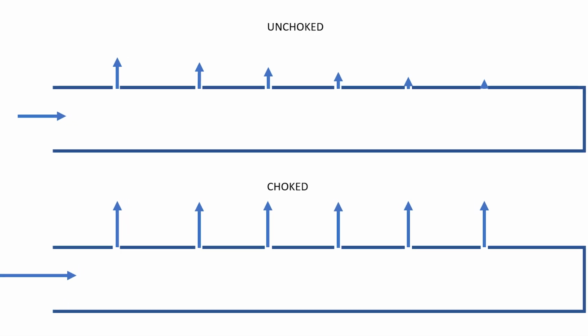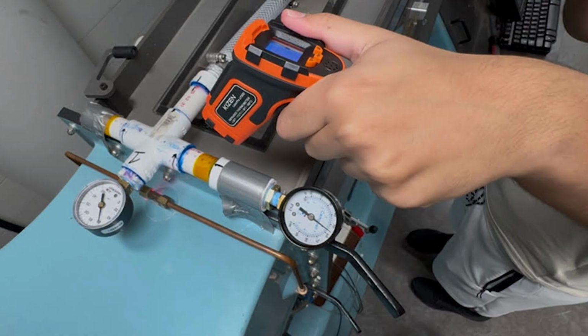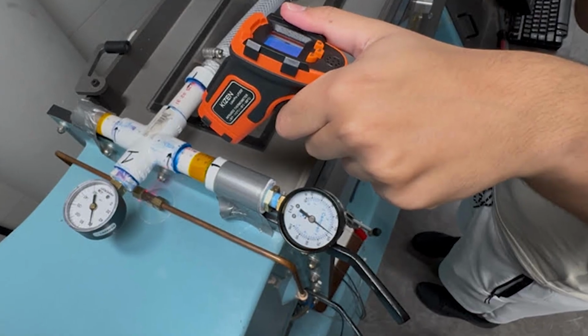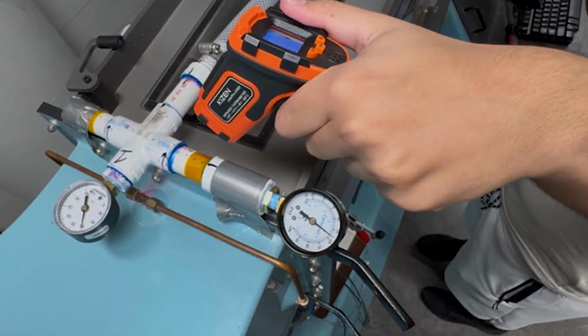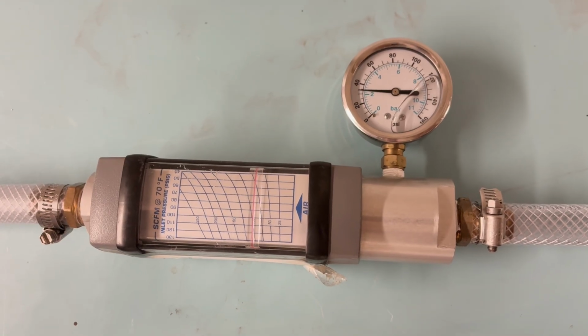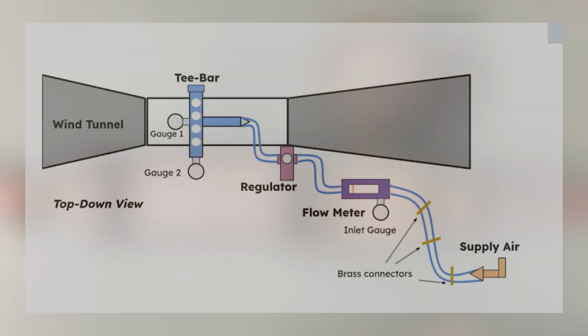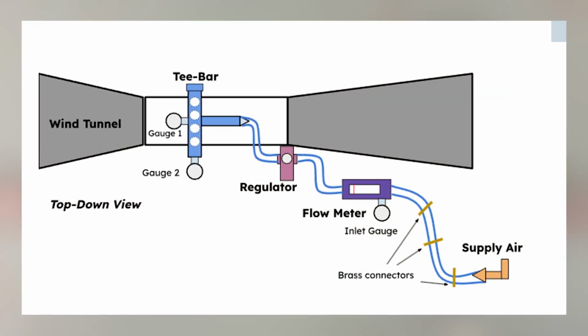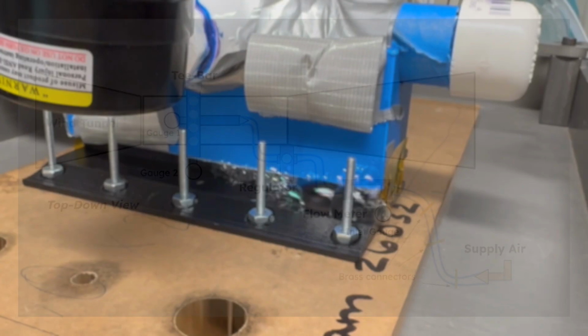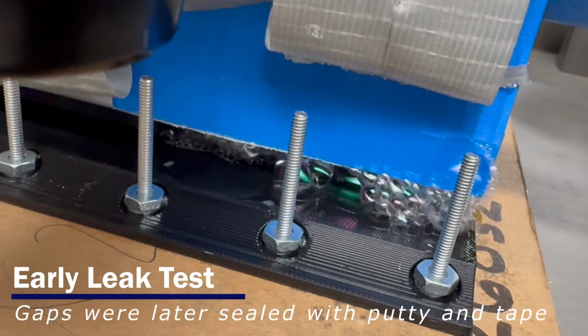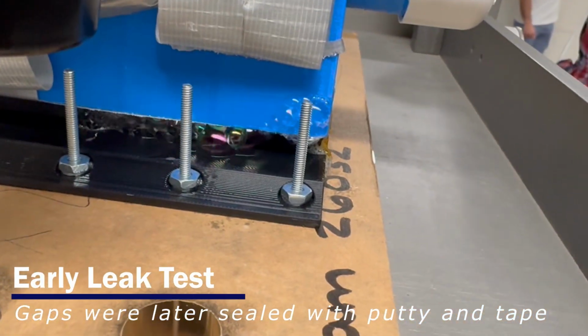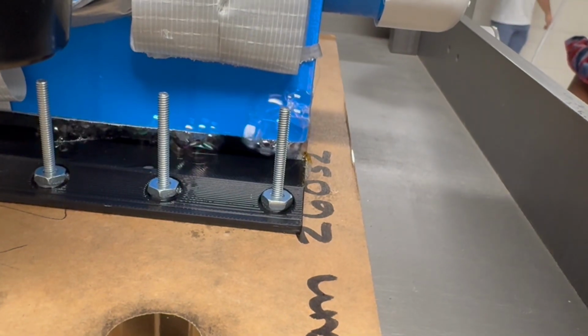We calculated mass flow rates by measuring the hole exit temperature during preliminary secondary flow system tests, later buying a flow meter to measure this directly. The final system features the flow meter, T-bar, and a pressure regulator between the two. We verified this system through multiple full pressure tests and leak analysis by applying soap to joints and monitoring pressure drops downstream.